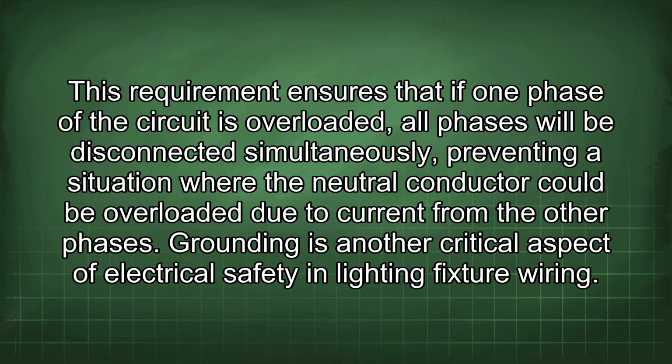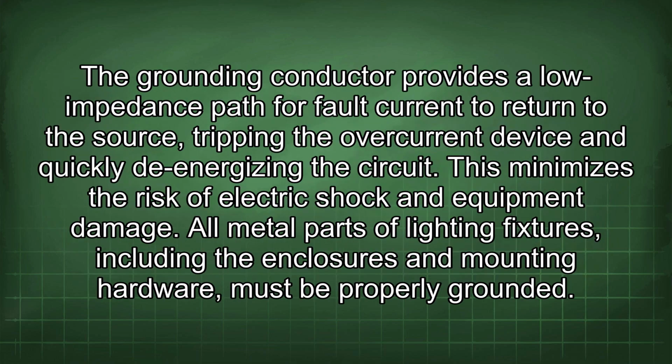Grounding is another critical aspect of electrical safety in lighting fixture wiring. The grounding conductor provides a low impedance path for fault current to return to the source, tripping the overcurrent device and quickly de-energizing the circuit. This minimizes the risk of electric shock and equipment damage.